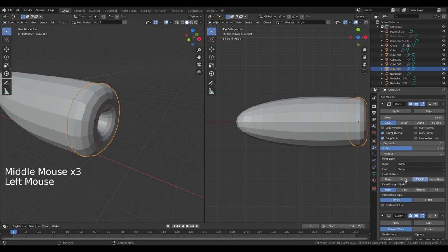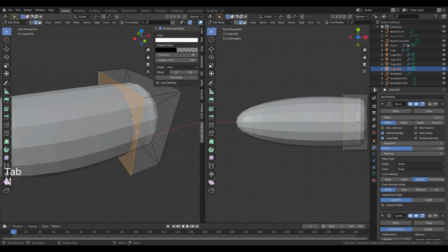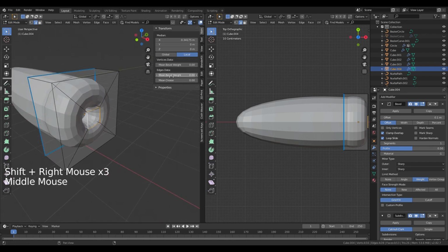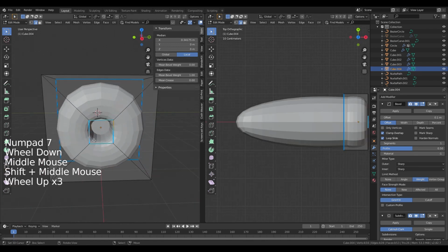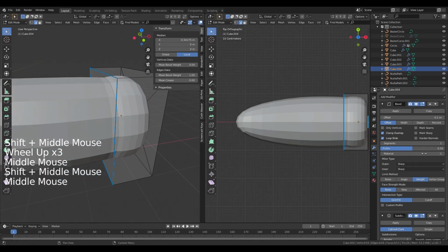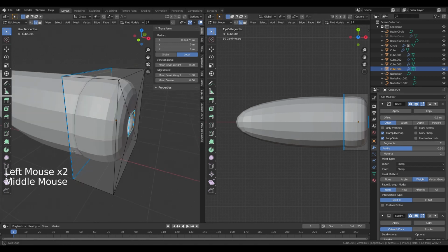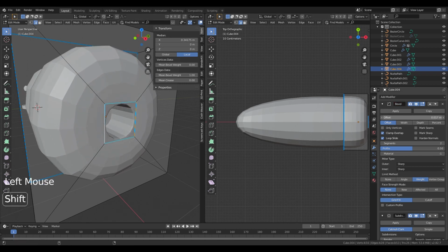Now I'm going to go into edit mode again, press N, and in the item menu, I'm going to increase the mean bevel weight to 1. Also going to choose the front edge, and I'm going to increase the mean bevel weight there as well. Now that I have these sorted out, I just want to increase the segments slightly, maybe pull them back. I just want to see what happens to the edge. So I want to have a sharper or, let's say, smoother edge. Maybe smooth like that works fine.